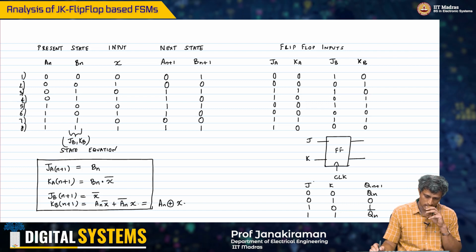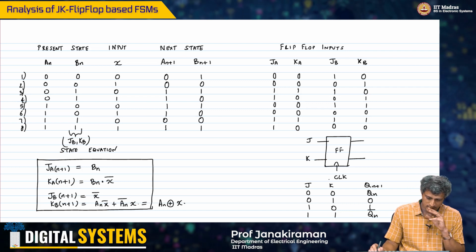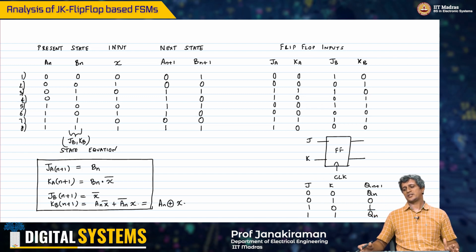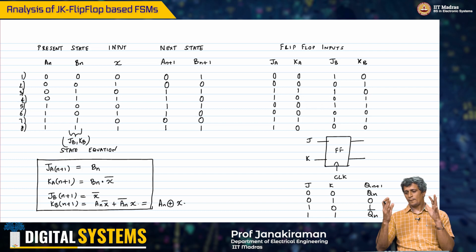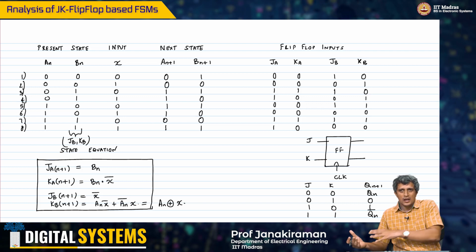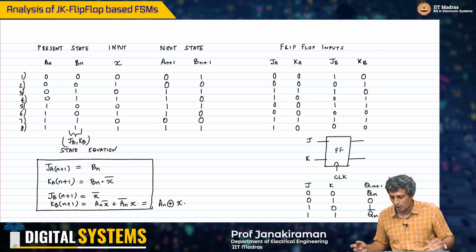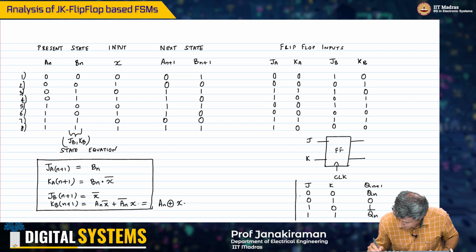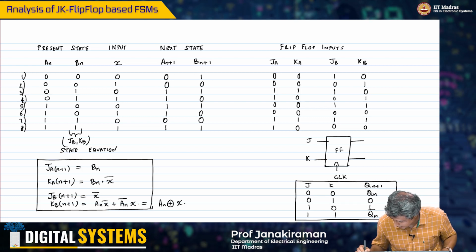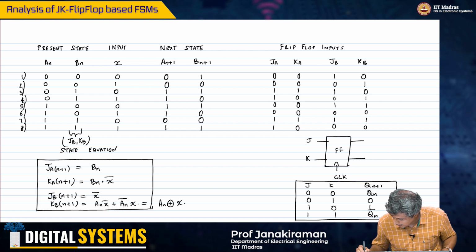So 1 0 1 0 1 0 0 1, essentially this is the next state of the flip flop. So in this example we had to go through this additional characteristic table mapping, because of this more complex state characteristic behavior of a JK flip flop compared to a D flip flop.